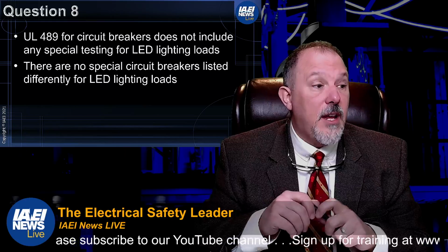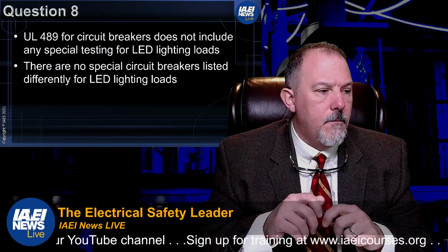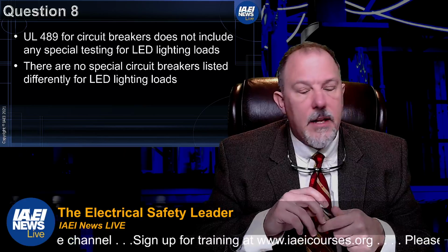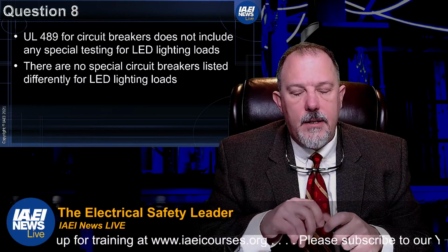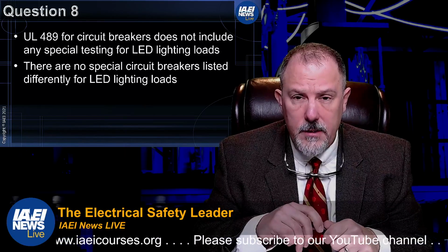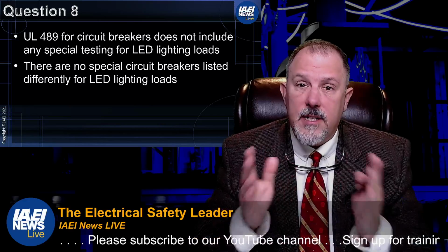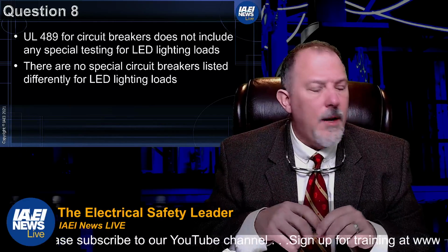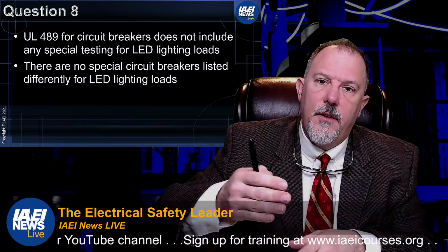Places where I know there's heavy use of LED circuits are grow facilities, right? Commercial buildings might use a lot of LED drivers in a string on the same circuit. So my suggestion would be, understand the inrush currents.